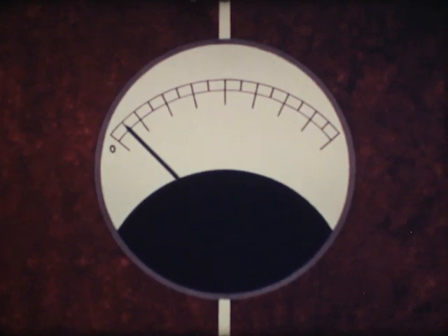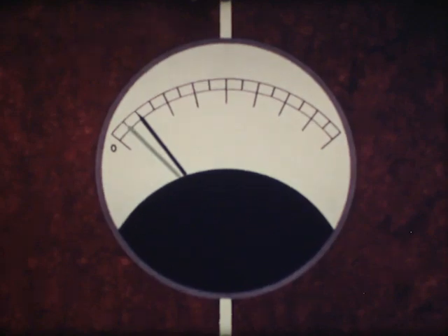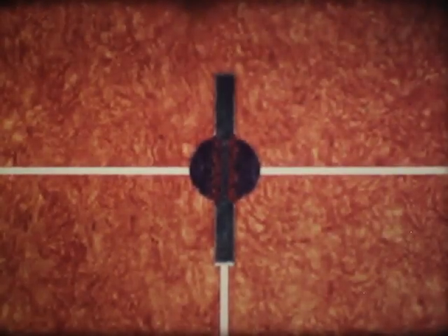However, if we measure this current, it will be seen that the meter indicates a slightly higher value. The reason is that some of the holes diffusing from the emitter into the base will not be absorbed by the collector, but instead will recombine at the surface of the crystal, and thus cause an increase in the base current. This effect can be largely avoided by increasing the surface area of the collector-base junction.